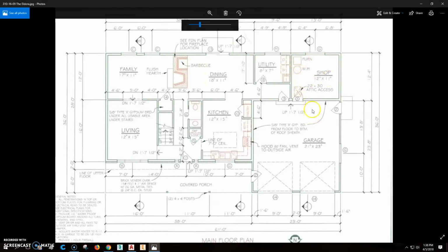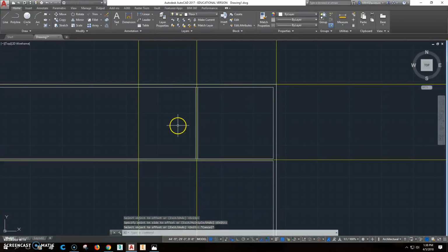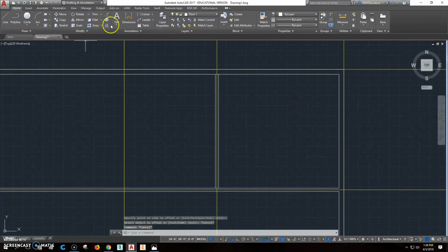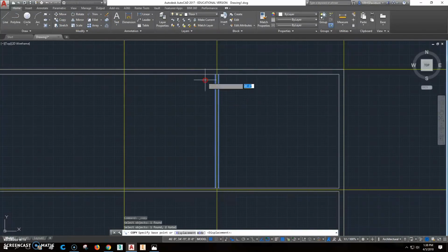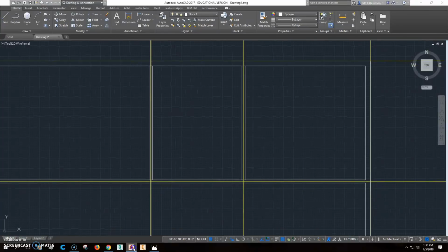We'll go back. Oh, look at this right up here. That's 9 foot 6 to this wall right here. So let's go here. We'll go offset 9 foot 6 inches. That wall. And so what we'll do in this case, we'll go ahead and just click copy, because we've got this wall established already from, say, that intersection there to this intersection, and that puts that one in place.